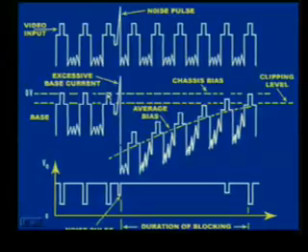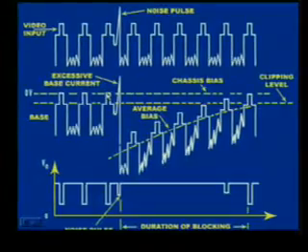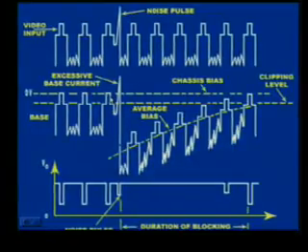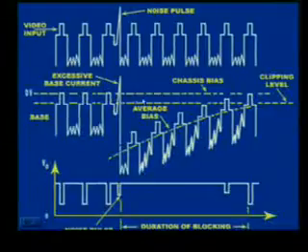We have been discussing that sync pulse separation is dependent on the amplitude, and as soon as this sync pulse reaches the sync pulse separator, they are separated. Since the noise pulse amplitude is more than the sync pulse, it will also be separated, and if it is separated, it will go to the horizontal and vertical oscillator and will affect the functioning of the horizontal and vertical oscillator.